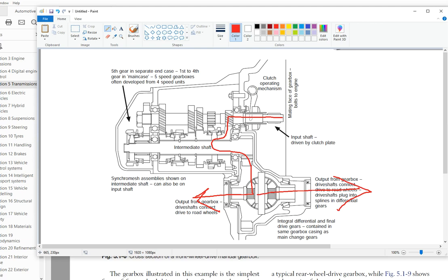Okay, so I'm looking again at the size of the gears, and this is the smallest one. This is the next inside, will be third gear, fourth gear. In direct drive, as you can see, there's further increase in diameter. The reverse for this transmission is not synchronized.